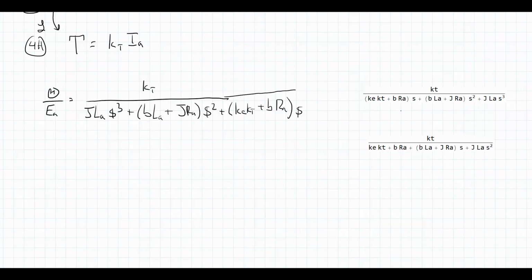So that's our first transfer function, angular position for our output to our input of the voltage in the electrical side. Notice the denominator, well, really the whole transfer function has parameters from the electrical side, the LA, the RA, the mechanical side, it has the J, it has the B, and from the motor equations, the KE and the KT. All of it appears in this one transfer function relating a mechanical output to an electrical input. And this all came from the original equations because it's a position which was an output that appeared and a voltage was an input that appeared.